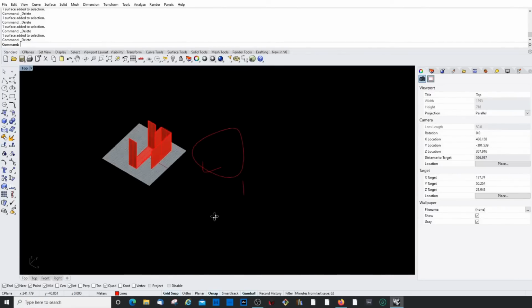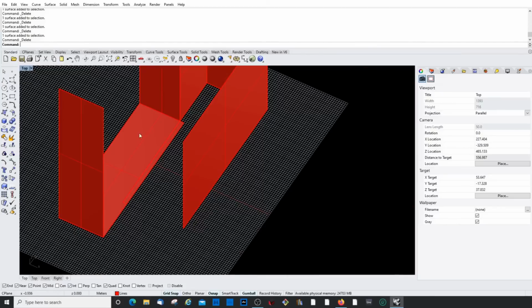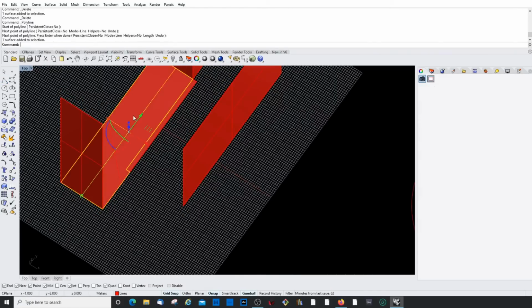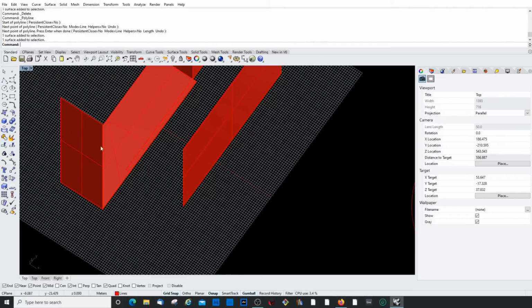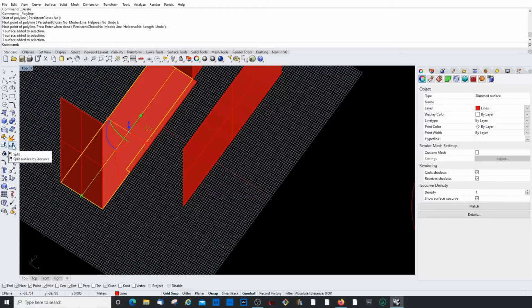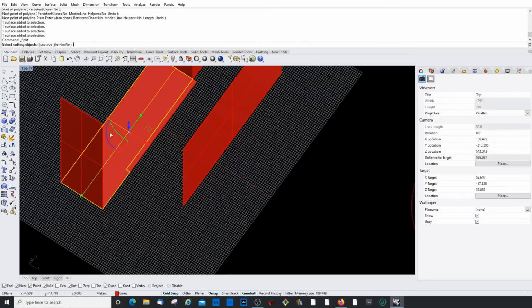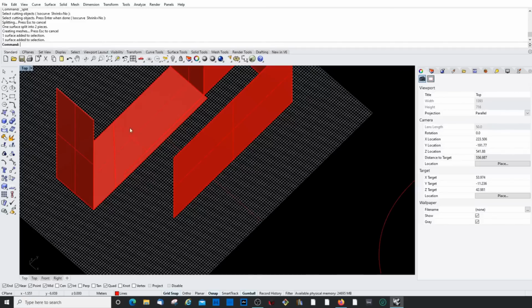Trim would be if I want to make like a special cut through that geometry or that surface. For example, I want to cut here. I want to cut through this middle bit to just a random point here. And I could select this and trim. Sorry. That would be split or cut. I call it cut. It's actually split. It splits the thing into parts.